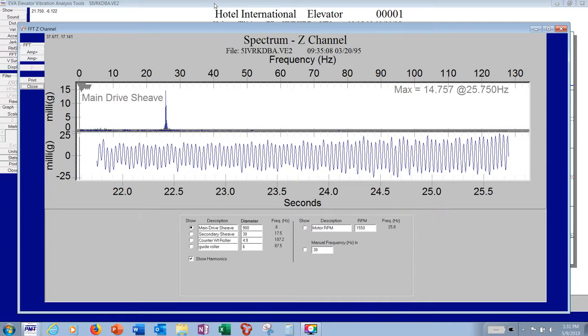In general, as you get closer to the source of vibration, the vibration level increases. The frequency did not change, so we're going to say, okay, ropes are not a related issue here. We're just getting closer to the source.